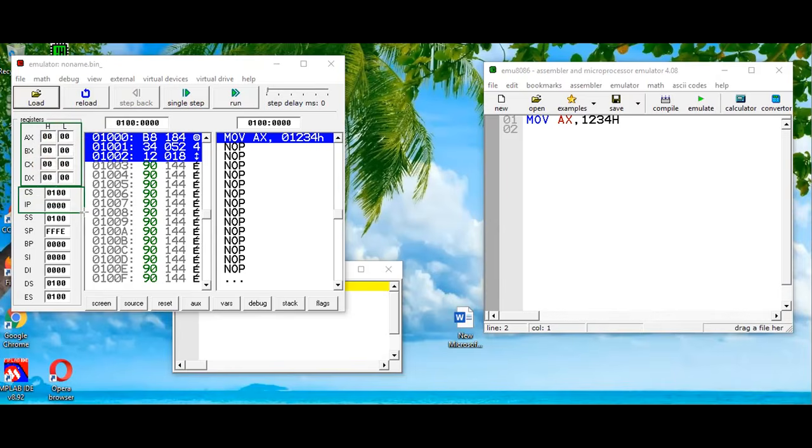We have already discussed the topic of physical address generation in theory classes. So we know that the physical address of each memory location attached to 8086 is 20-bit, but the 8086 microprocessor is a 16-bit microprocessor, and we cannot access a 20-bit location using a 16-bit processor. So there are two 16-bit registers involved to generate the physical address, and those two registers are the segment register